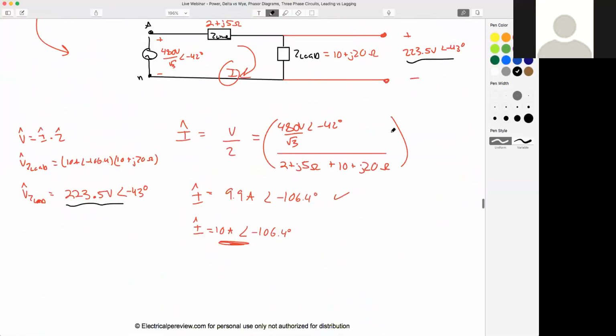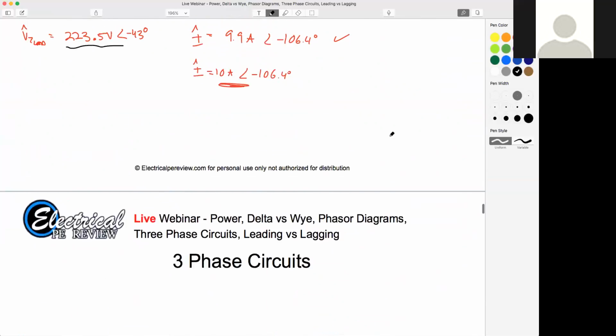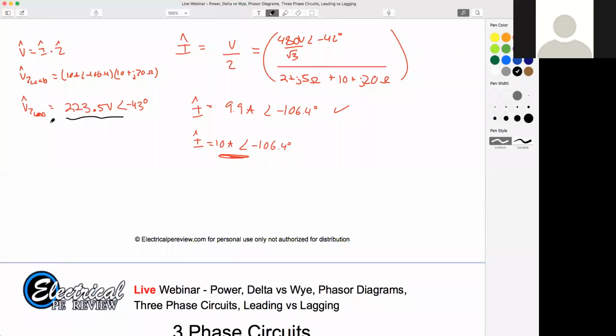So now we don't just want magnitude, we also want the angle. So now what do I have to do? So this is single phase. What do I have to do? So we know we have to, good, Kahina, fantastic, Greg, fantastic, Alex, fantastic, bingo, you guys are on it. So not only do we multiply the square root of 3 times our magnitude, we know we've got to shift up, right? We've got to lead again by 30 degrees.